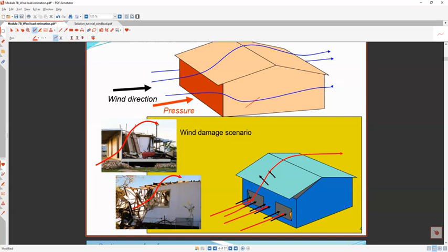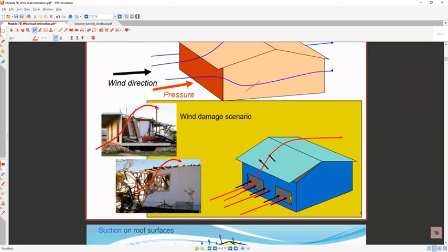Imagine a building which is 20 meters or 15 meters long. If wind flows like that, you'll have an additional effect of drag. Drag means it is as if something is pulling the building. The aeroplane and those are subjected to drag because you are moving with a speed through a certain fluid. So there are two types of drag. That's again all fluid mechanics, which is another interesting area of study. If you study fluid mechanics, you see the main thing is the pressure drag.